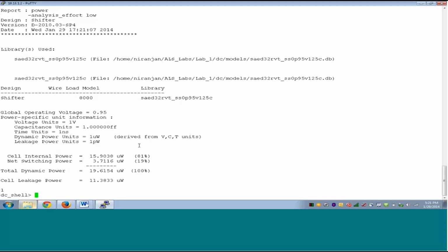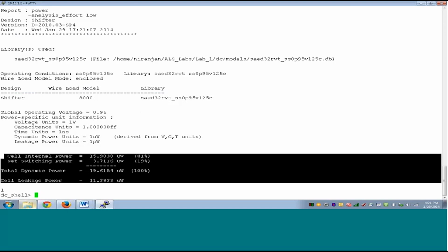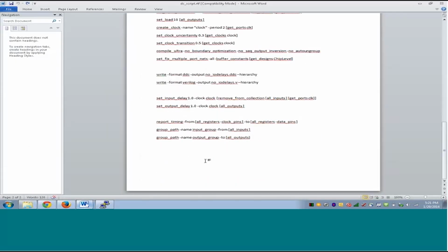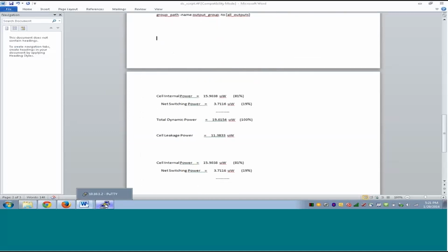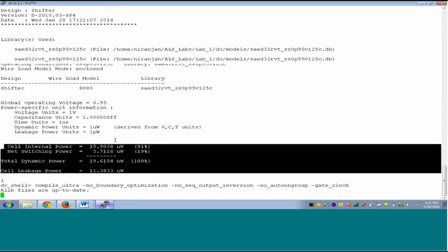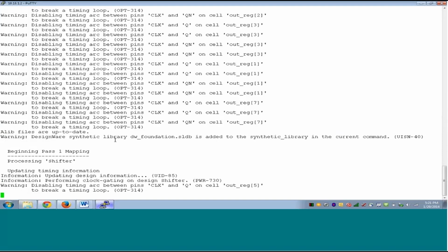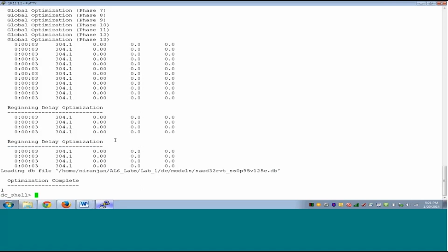So these are the power numbers. Let us move this. Just move these power numbers without clock gating. And what I will do now is I'll say wait clock. Area is not increased by much, I guess just one cell area, and I'll do a report power.